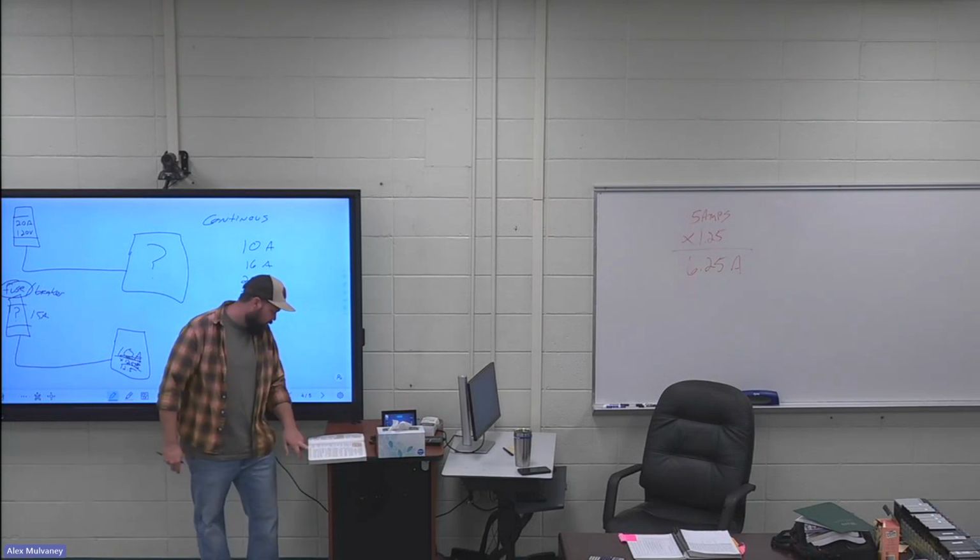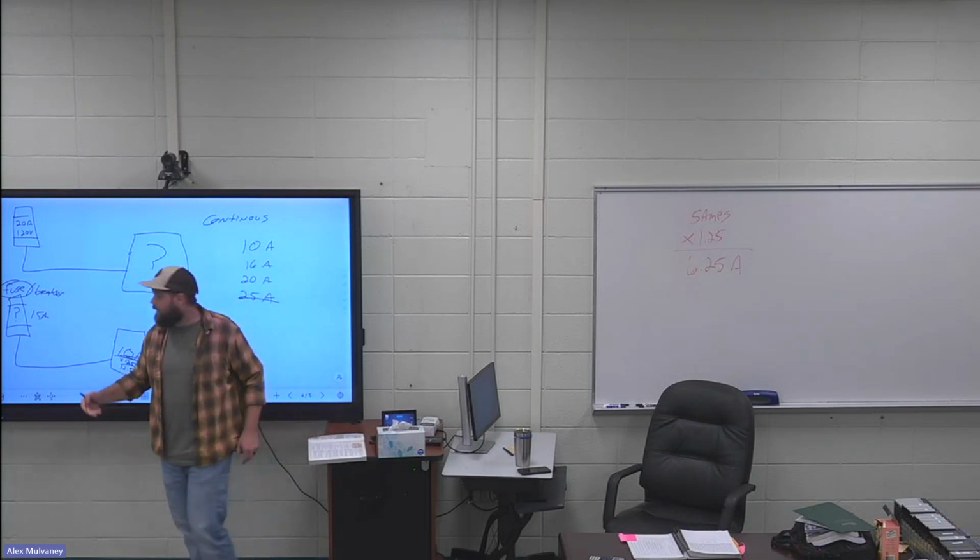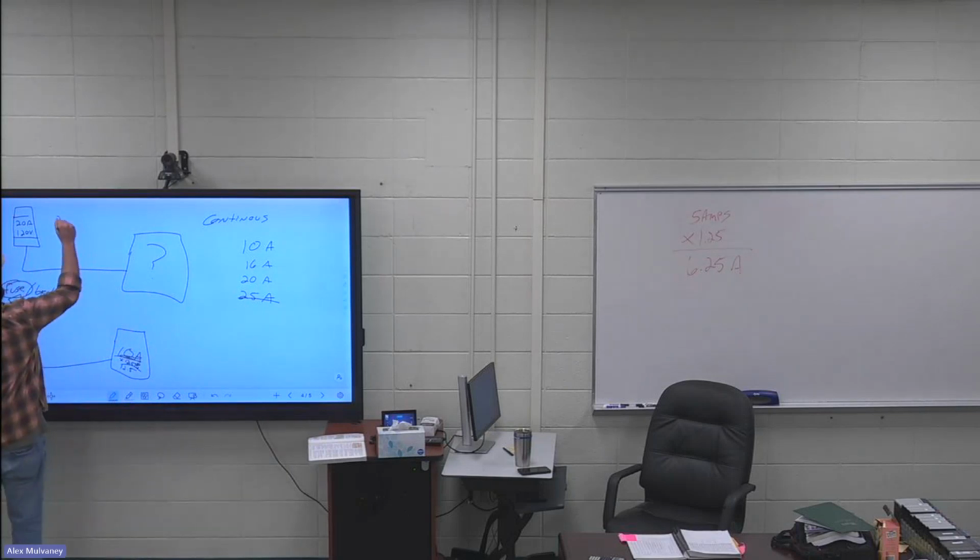Going to page 2. This is where y'all highlighted that blue or green highlight note on the right. So yes, where you can divide, you can take your 20 amps and divide by 125%. What's 125% as a decimal? 1.25, right? And what does that give me?